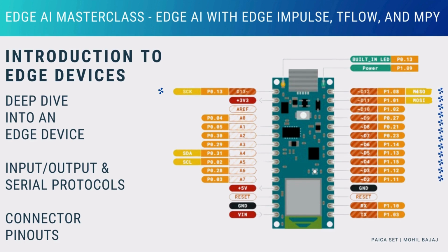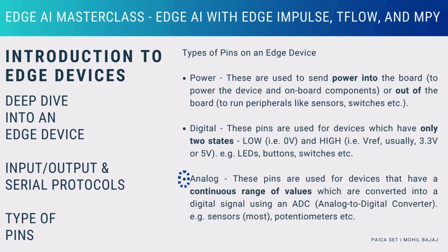The pins on the left, starting with the letter capital A, are the analog pins. The A-ref pin is for the reference voltage for analog devices, and we will look at it a little later in this section. For now, just understand that it is used for analog devices. These analog pins are used for reading variable signals, or readings from sensors like temperature, humidity, and light.